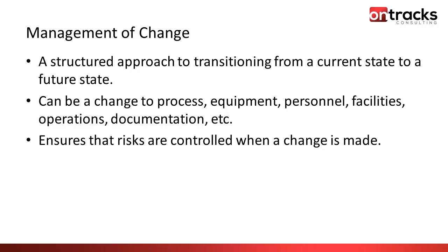So if you're replacing a part by another manufacturer that has identical specs, that would likely be a replacement in kind. Whereas if you actually have to do some level of analysis on the new part that's being installed due to changing specifications, that would be a management of change.